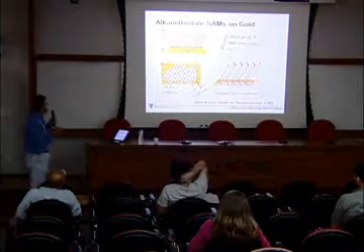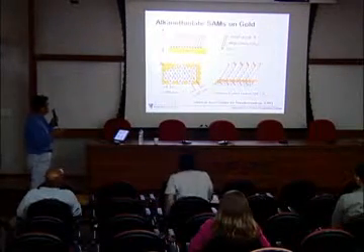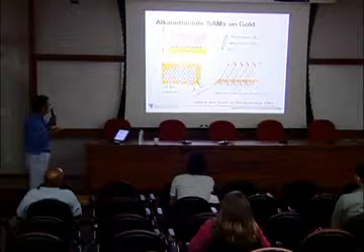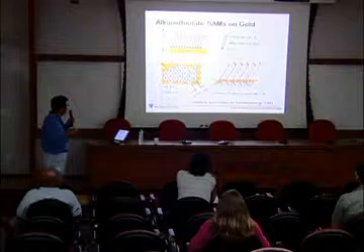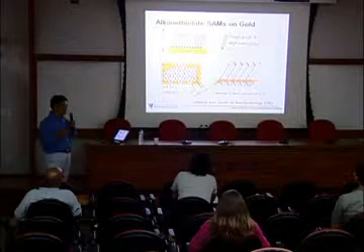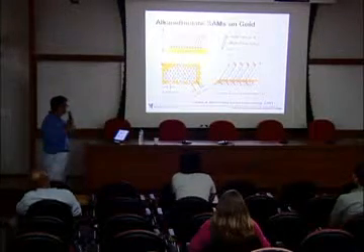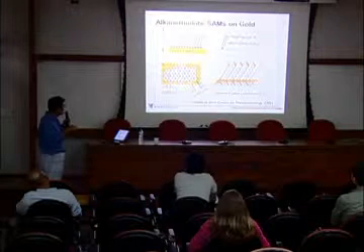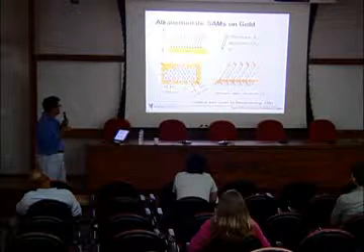Anyway, this alkane thiol is called a self-assembled monolayer. The stamp can be dipped in this solution, and then when we stamp it on the gold surface, the monolayer will be transferred like that. Then the area with the gold can be etched selectively. After that, this monolayer will protect the gold layer.